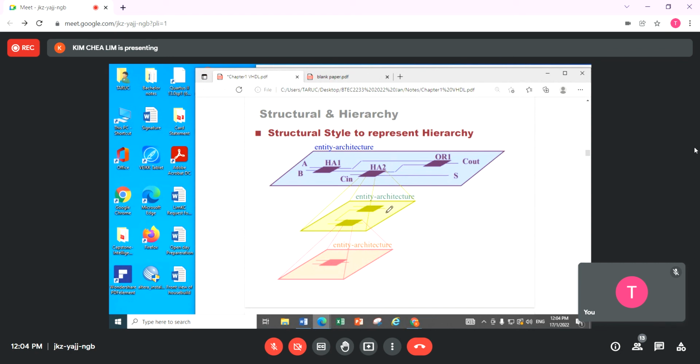So this part is trying to tell you that you can do hierarchical design. A slightly tougher circuit, you can break into smaller parts. You design from an easy one first, then combine them. Confirm this one is working, then come to here, no error. Come up to here, also no error. That's what we want. So for a difficult design, don't always start from the top. Always start from the very simple bottom.